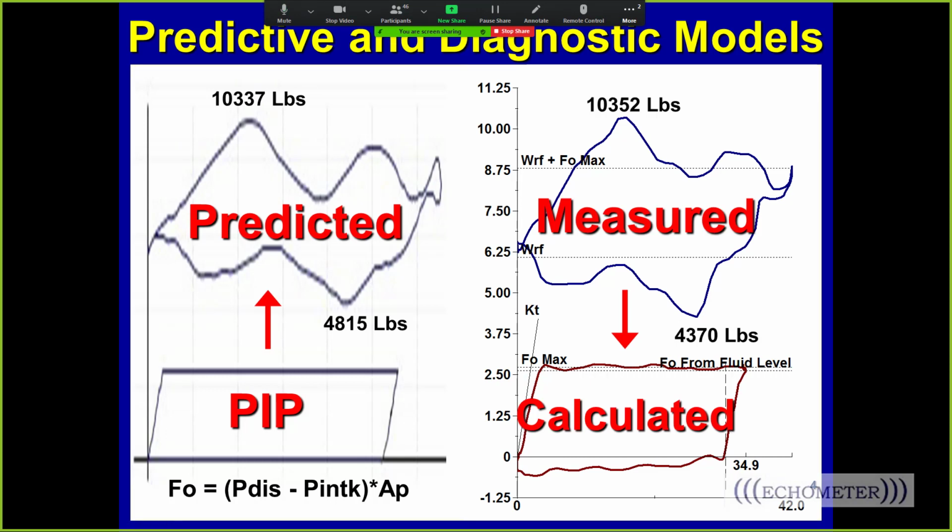and that's what is acting at the bottom of the rod string. Now, when you look at this, you see that the peak load here matches really close, and that's because we match the fluid load very close on the upstroke. But this is a plot from the T2M software, and notice that here the pump card load goes below zero.